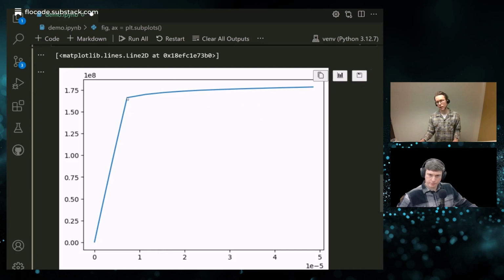Yep. And then you have this post-yielding curve until you reach final compressive failure in the concrete. So this is a great example of what you mentioned earlier, where once you finalize your geometry section, you're then wrapping it in all of these various hidden functions, your constituent or constitutive laws, that allow you to create this exact plot.